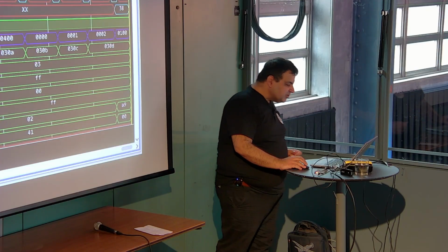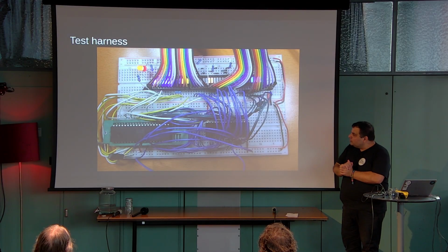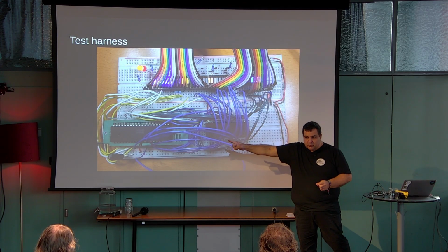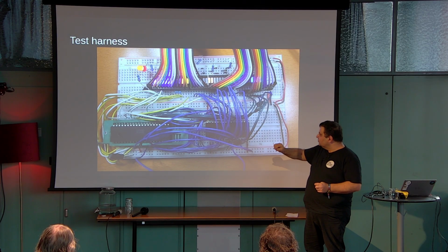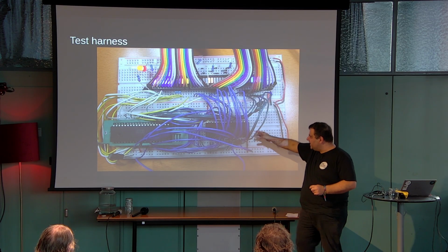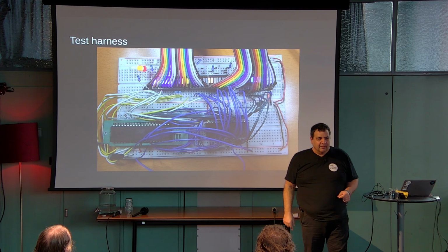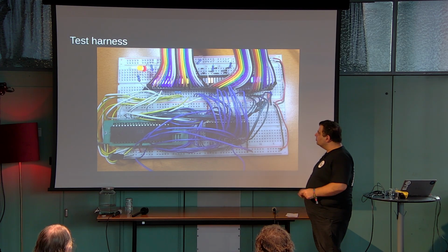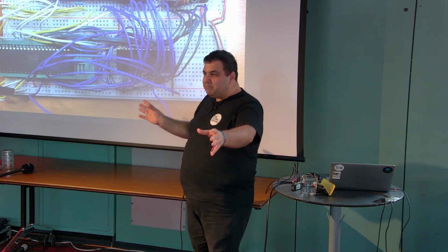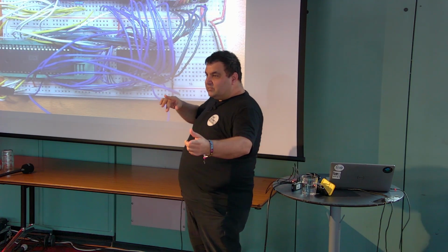So let me introduce you to another computer I built. What you see here is a Western Design Center 65C02 connected to 64 kilobytes of static RAM. Technically, that's 128, but you see this black line here that pulls an address line low, so that's 64 kilobytes. And that's a computer, right? CPU, memory, a computer. But not a very useful one.